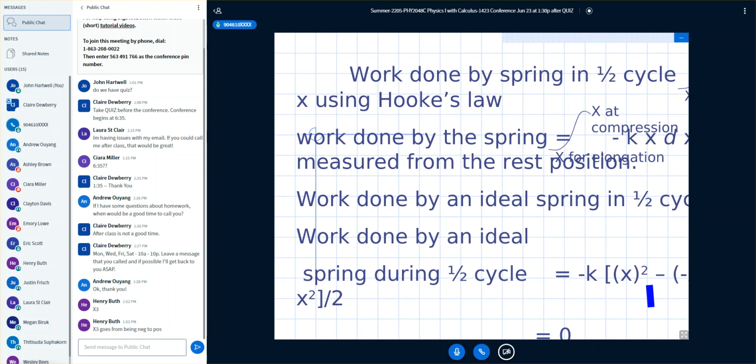If you use the trapezoidal rule or Simpson's rule to find the area under this curve, where I've identified x as 0 meters to some final value, in meters, does everyone see where there is more negative work done here than positive? Does anybody just want to give me a yes on that? I see what you're talking about. Yeah, it's a lot of area down there in the negative.